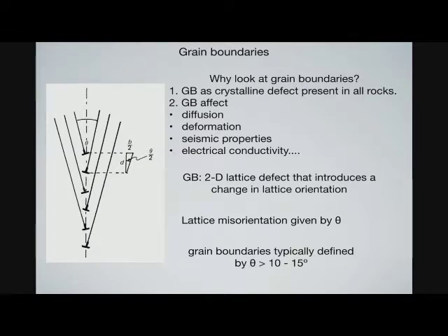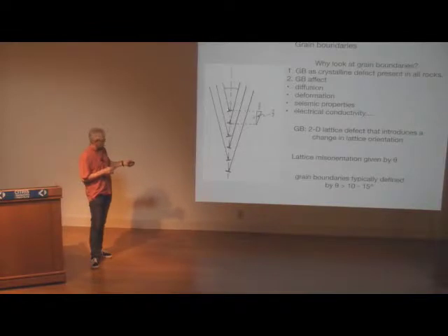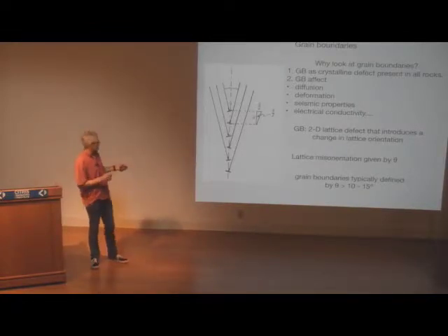It's a lattice defect, so the very simplest view is that you just stack up a whole bunch of dislocations, right? And the dislocations give you a distortion in the lattice. You can see the lattice planes here are at an angle, this angle theta, and depending on the dislocation spacing, you get a relative orientation of the neighboring lattice planes.